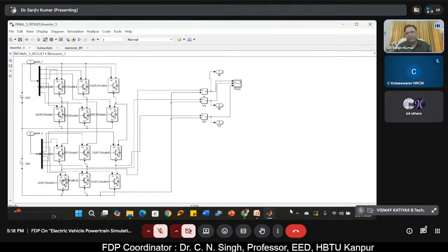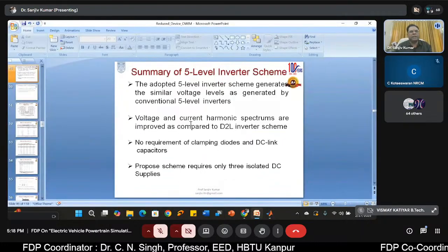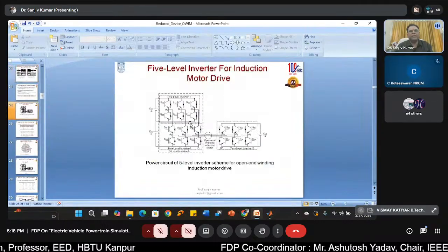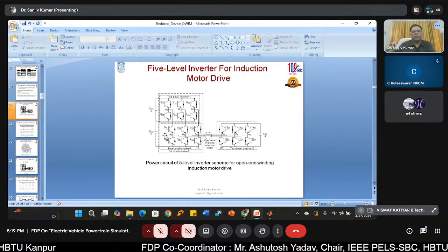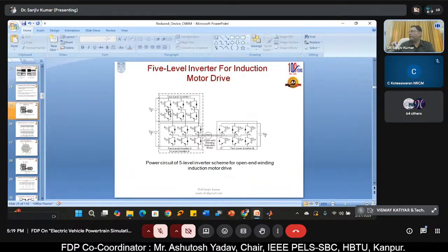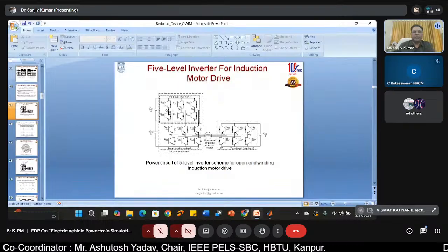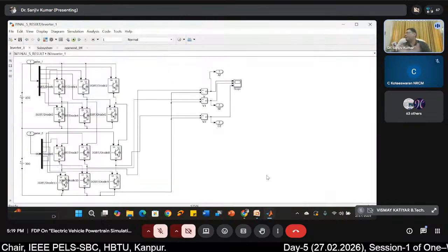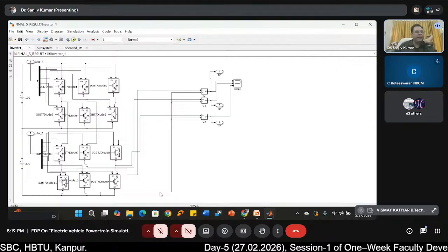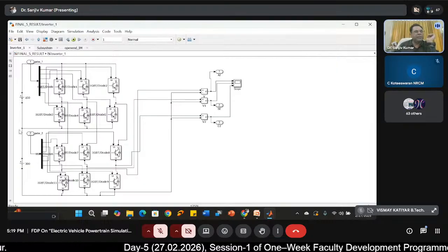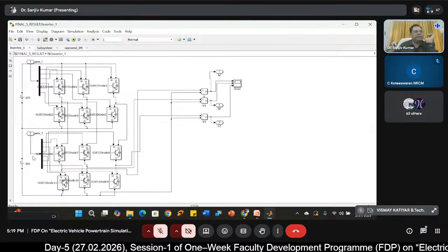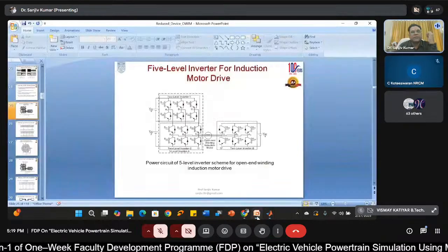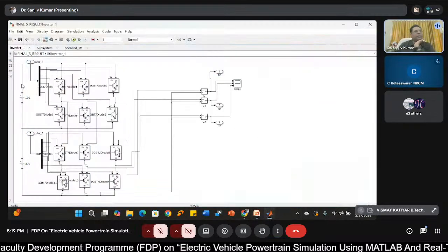If you remember my PPT, just cross-check. Look at this, the simple two-level inverter. Via this, we are getting the 3-level inversion operation, and the right-hand side is a 2-level inverter. The same things we are doing. Clear? And you can see the voltage levels. This is VDC by 5, then this was 2 VDC by 5. Let me say VDC by 4 and 2 VDC by 4.